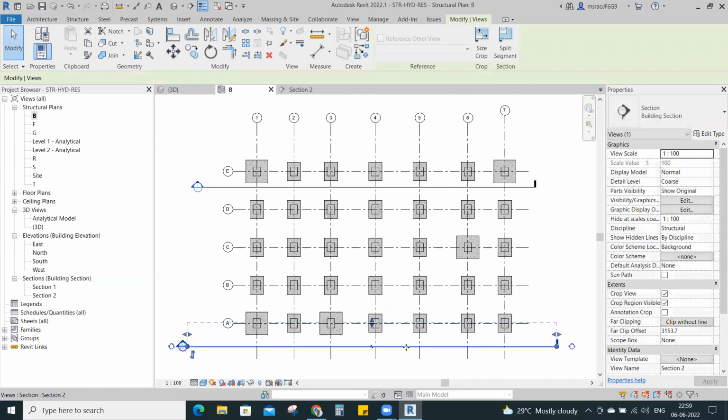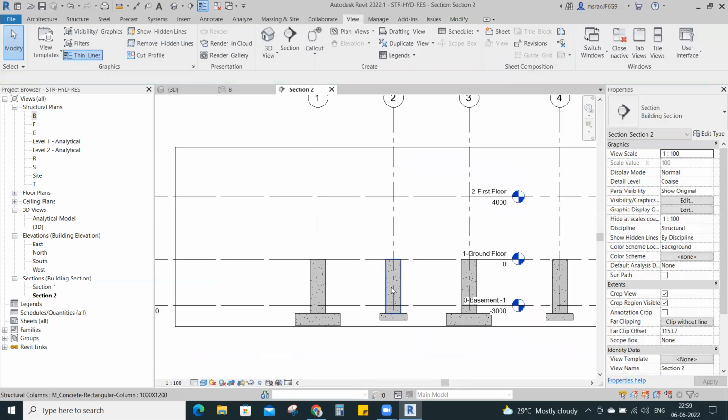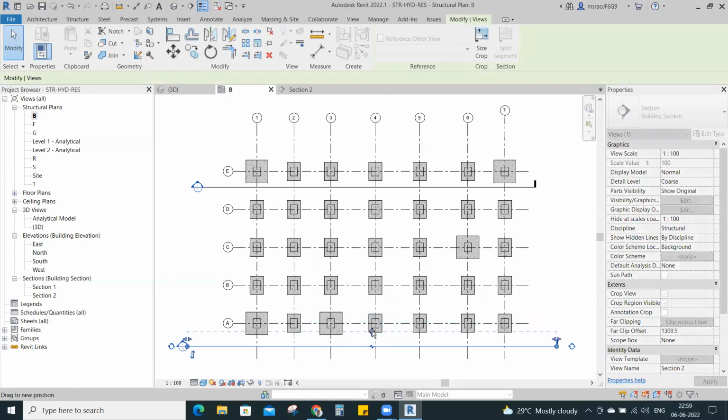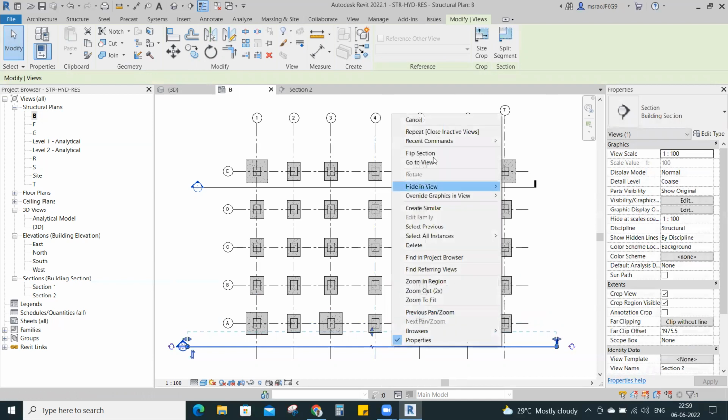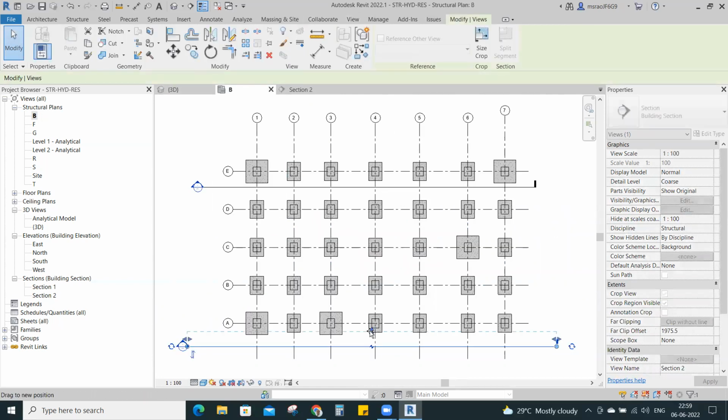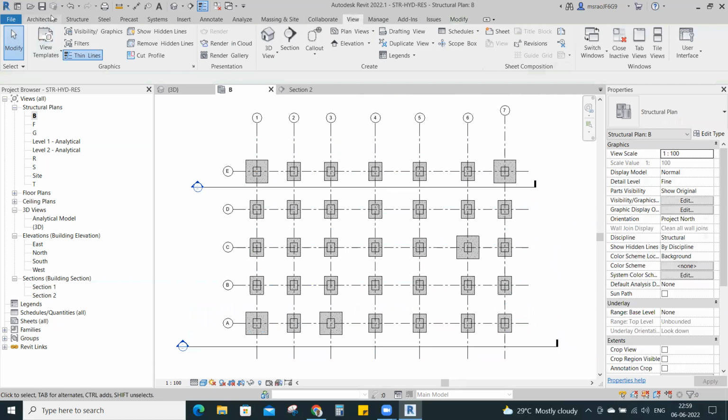If you cut up to this, you can see up to the particular area only. Let's say for example, if I reduce up to this, I can see only footings. No columns. This is the range, how much we can see. If you go up to this, you can see everything. This is the view clip range. Can you remember? This is useful to check the sections and check the 3D views to navigate our model properly.